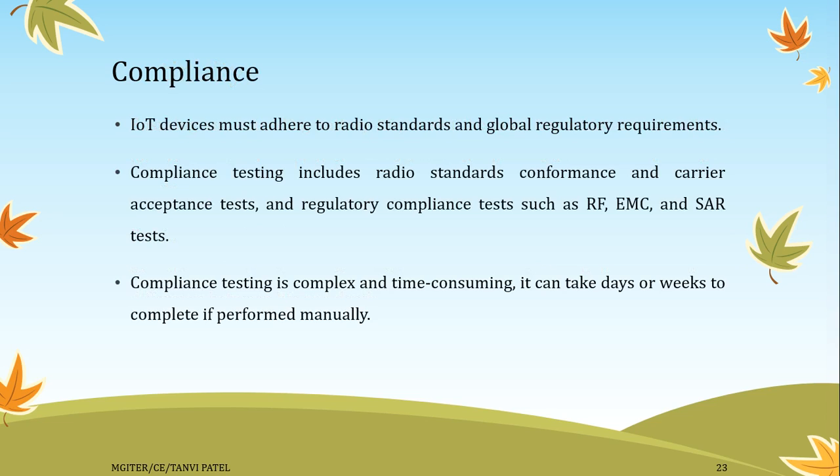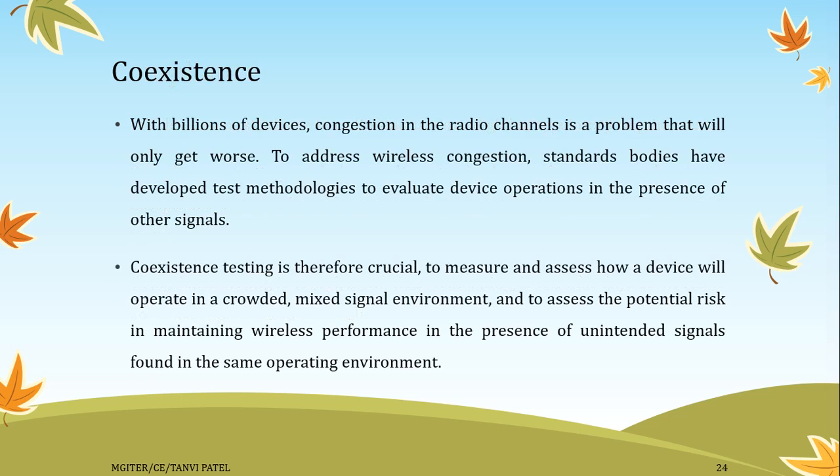Next is compliance. IoT devices must adhere to radio standards and global regulatory requirements. Compliance testing includes radio standards conformance and carrier acceptance tests, and regulatory compliance tests such as RF, EMC and SAR tests. Compliance testing is complex and time consuming. It can take days or weeks to complete if performed manually.